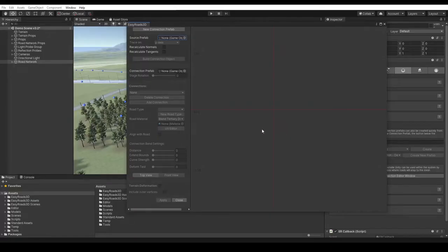This is important. To define a connection area, the vertices parts of this connection are selected by pressing Shift and drawing a rectangle around these vertices. After all connections are set, we click Apply.